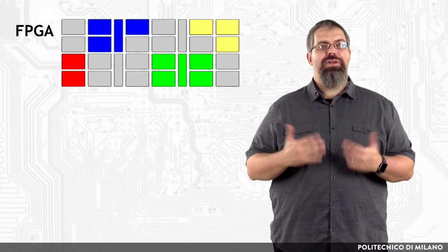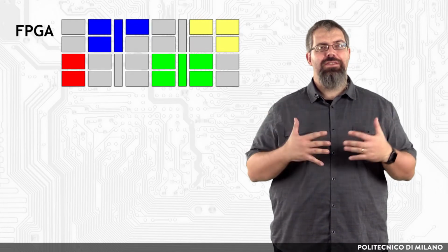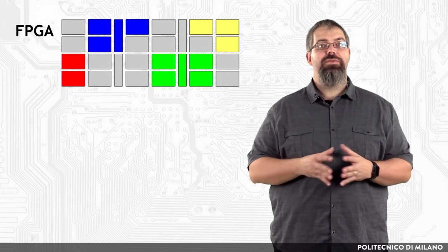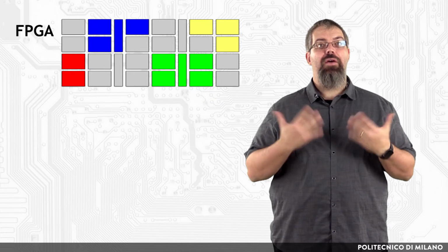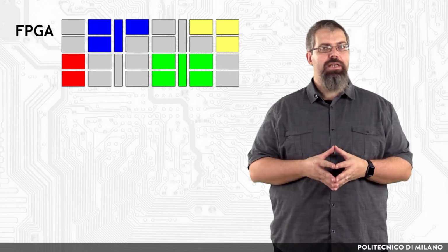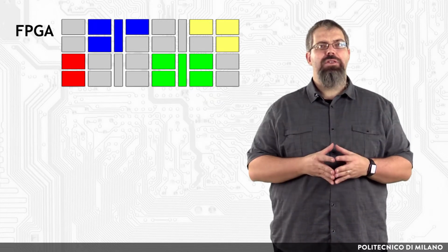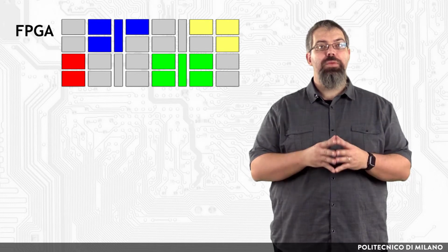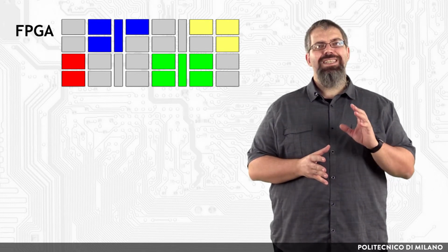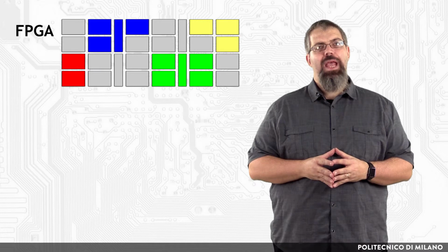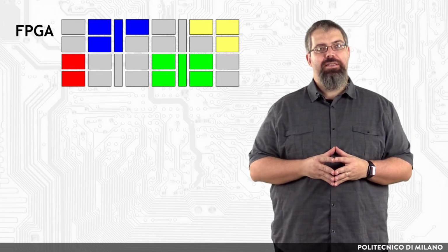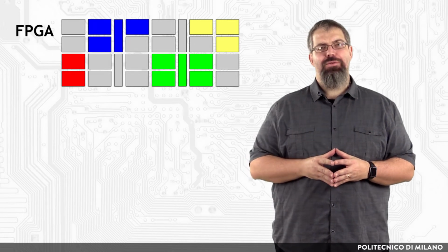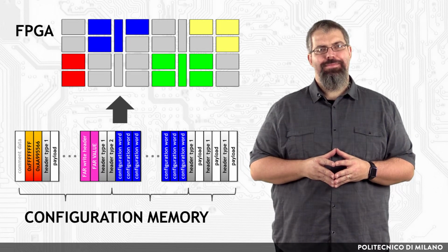The building blocks presented so far interconnect together in the device to create a communication infrastructure composed of the communication lines and IOBs around a bidimensional array of CLBs, which covers most of the available die area and represents the true FPGA building block. But what does it mean to configure an FPGA? How are all these elements going to be used to implement a desired system? Let us try to find out more.